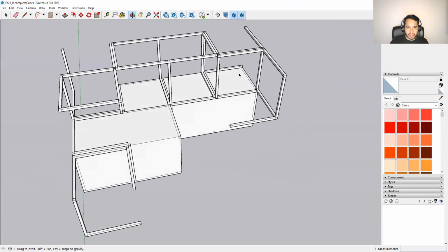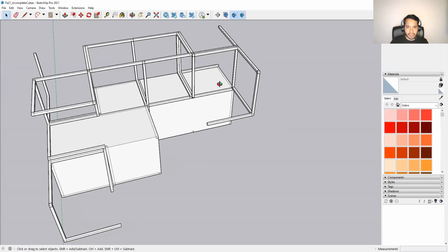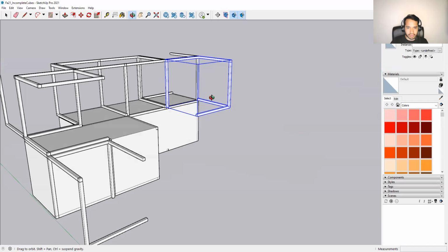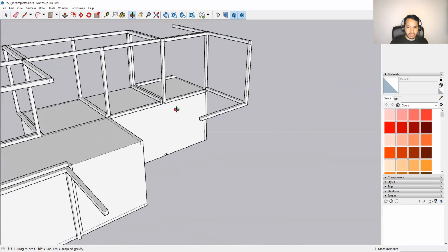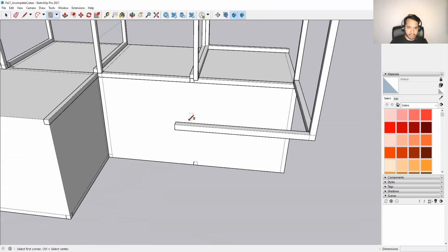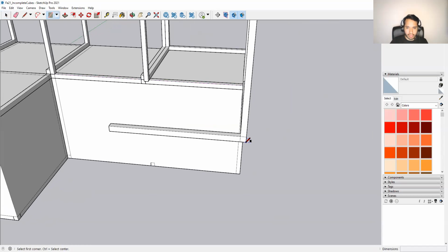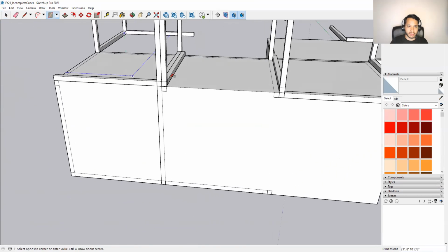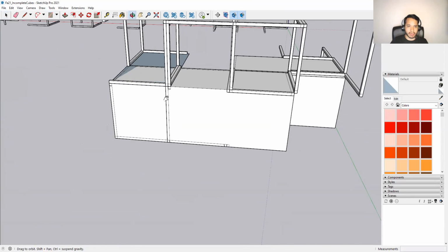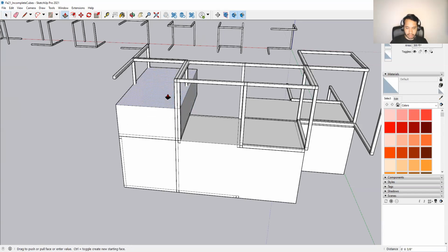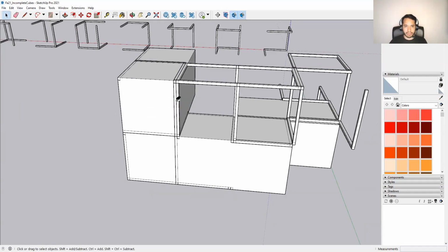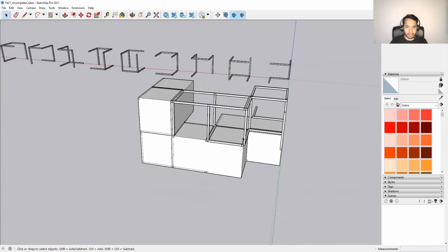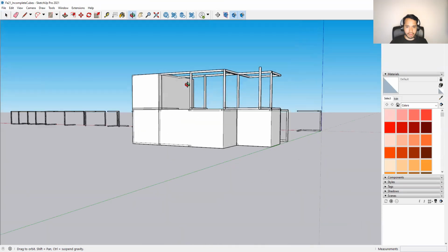Now I'm going to come up over here. And I really like this incomplete cube that's just hanging off on its own, just cantilevering. So what I want to do is I'm going to use the rectangle tool. And I'm going to click on this corner and come over here to that corner there. Use the push pull. I'm going to go up 12 feet. Okay. Triple click, 1, 2, 3, right click, make group. All right. And so there we go.